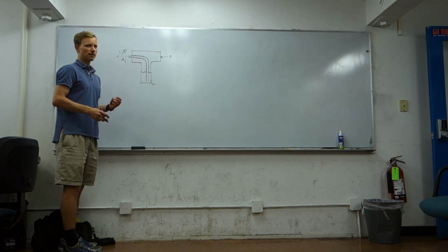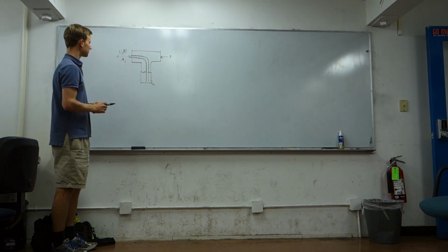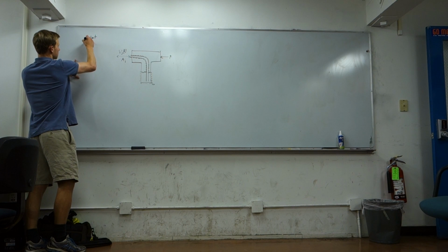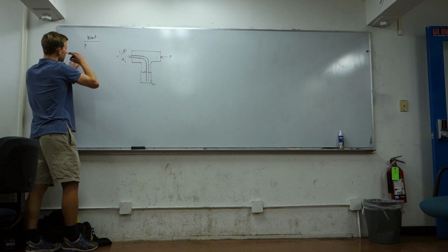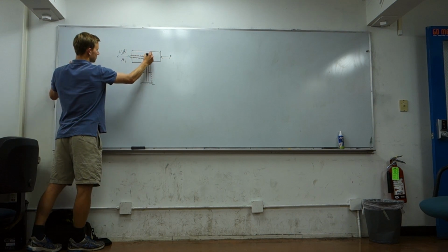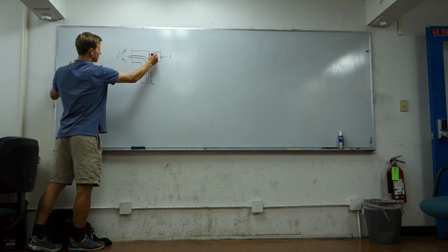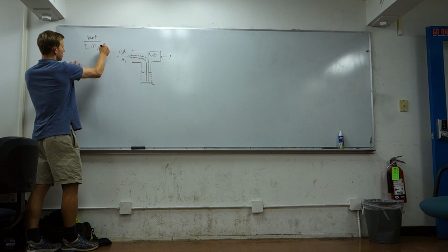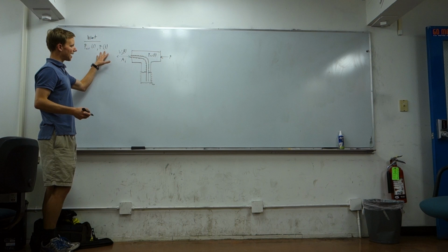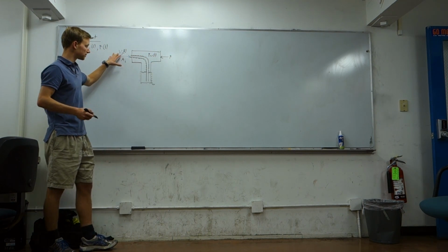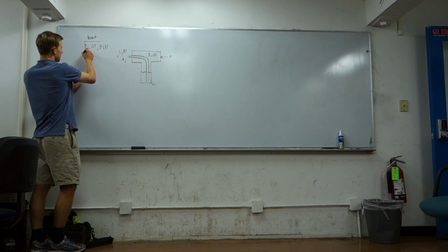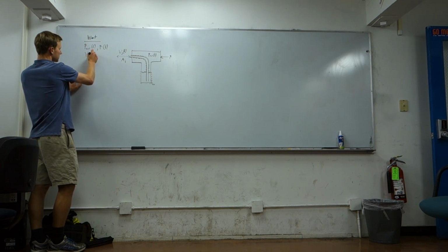And let's think about what our unknowns are here. So we want to plot P, and I'm going to say it's P air as a function of time. And that'll be the pressure inside this chamber. We want to plot force as a function of time. And we know, right off the bat, that force will probably be a function of this velocity, because we know from momentum balance that there's going to be that term, the flux term in there. So that's going to be another unknown. Vj is a function of t.